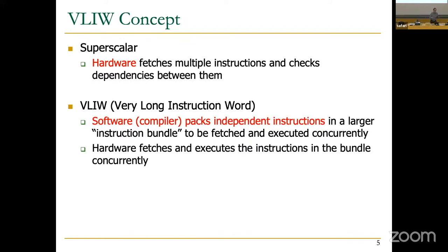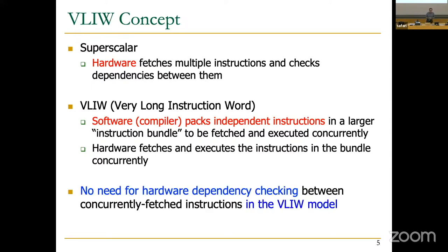Pure VLIW is very hard to achieve, of course, because it's very difficult to have a lot of independent instructions. I'm going to give you a flavor of it today and also discuss the difficulties. But basically, there's no need for hardware dependency checking between concurrently fetched instructions in the VLIW model. And in the real pure VLIW model, there's no need for dependency checking at all.